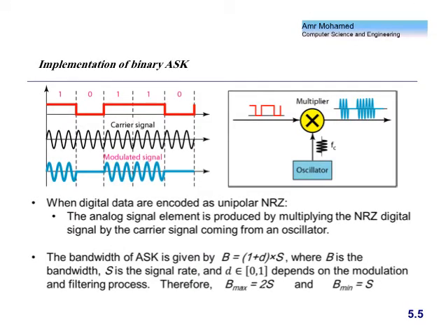So we have the NRZ, or the basic binary line coding scheme. So the 1 is interpreted as positive voltage and 0 is interpreted as 0 voltage. So the basic line coding scheme, and then instead of sending this signal as is, which we have found out has all types of problems, including high power, including DC component, including synchronization, including everything.